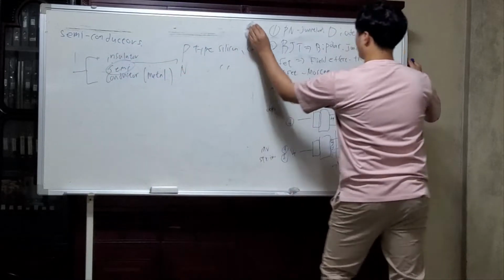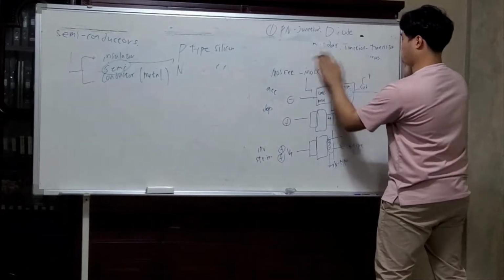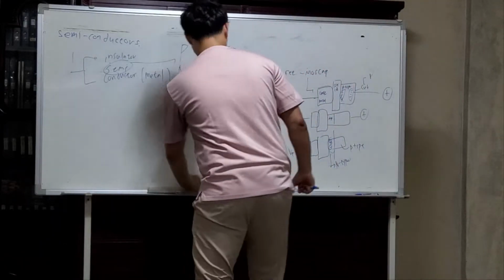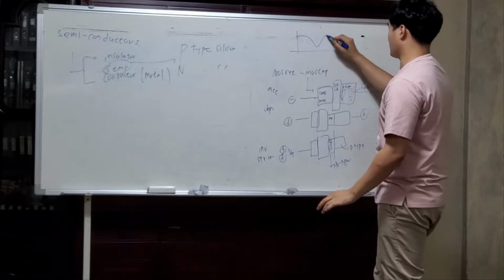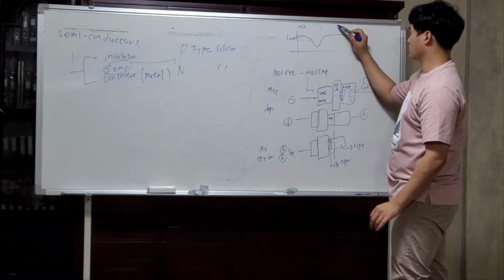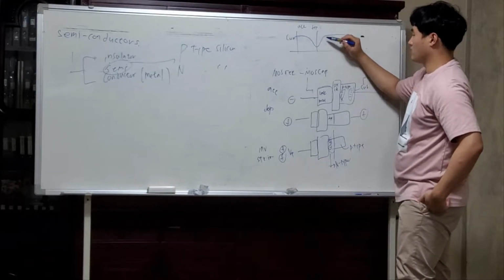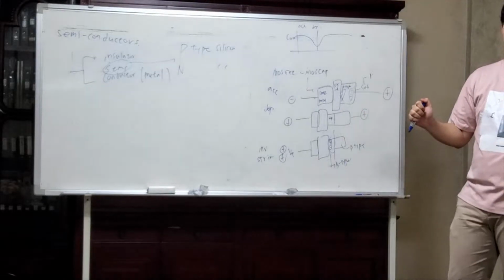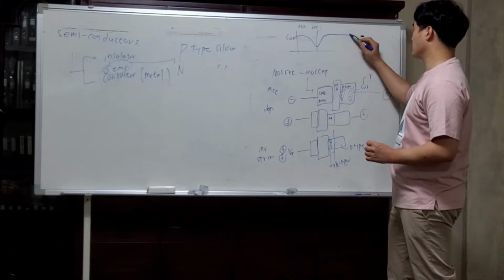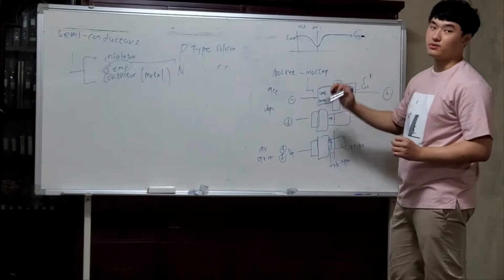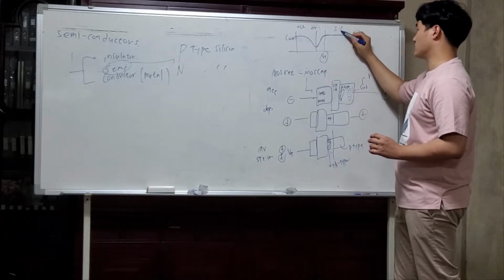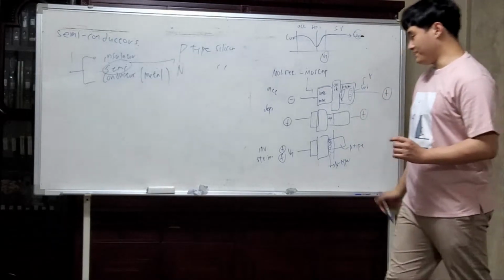Now let's explain the MOS capacitor. The capacitance will change like this: accumulation state, depletion, and when getting over to the inversion state, the capacitance of the oxide will increase, and finally saturate at its maximum capacitance. So this is the MOSFET.